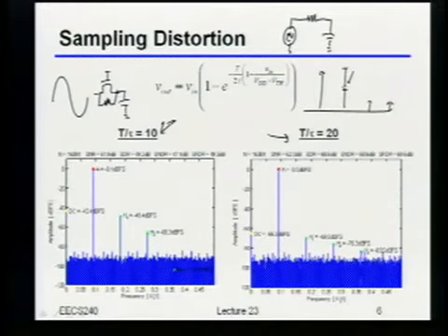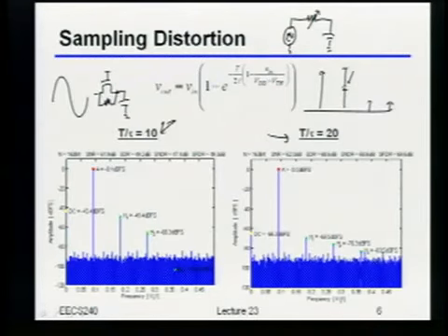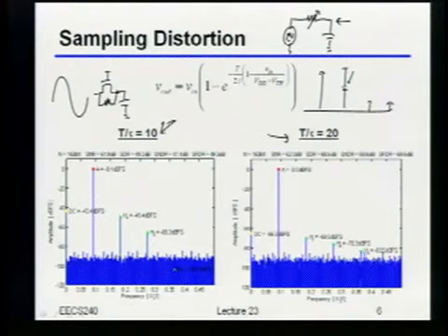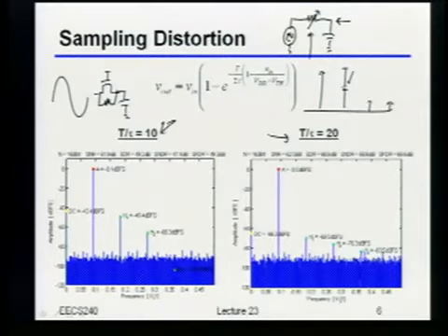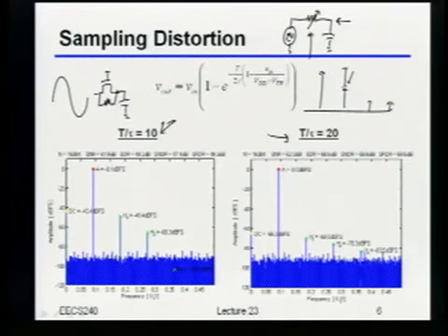the situation we're basically in just looks something like this. I have a sinusoid, some varying resistance, and a capacitor, right? Okay, so if I waited forever, or rather, if the sinusoid was super duper slow, what has to show up over there? Same. Yeah, it has to be the same, right? No matter how grossly nonlinear that resistance is, unless it completely turns off or something like that, eventually this output over here had better match the input, right?